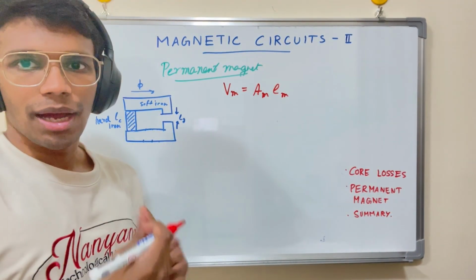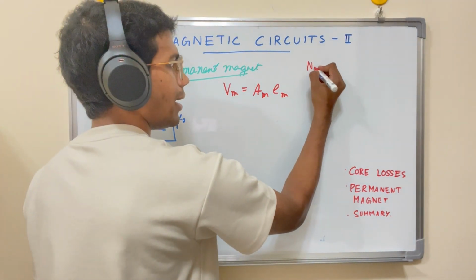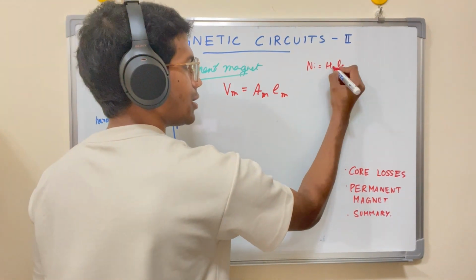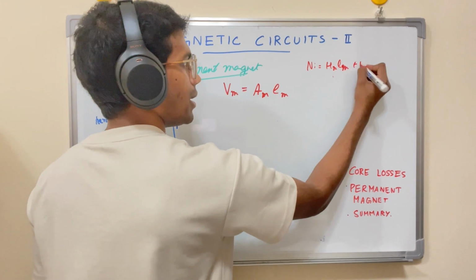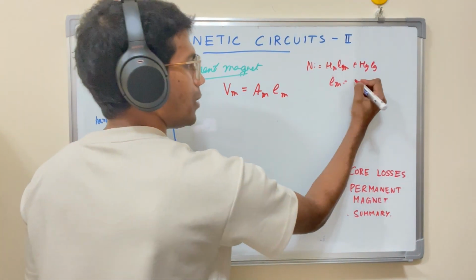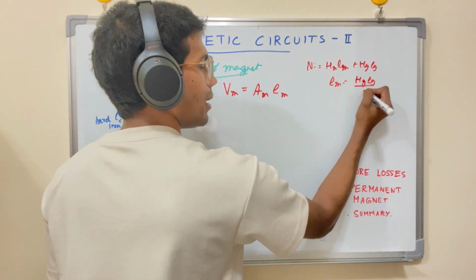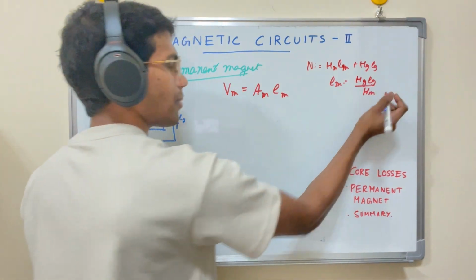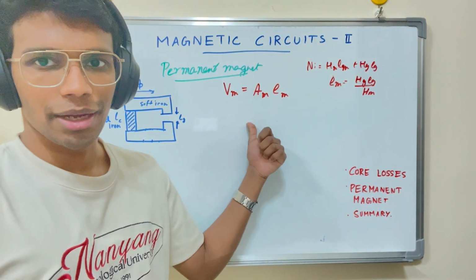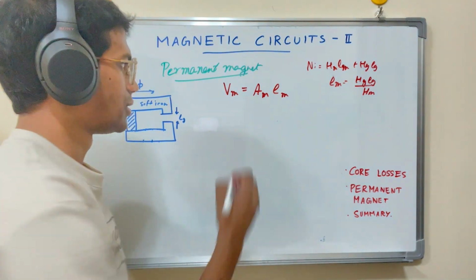That makes sense. Now we have Ampere's law, which states that Ni equals HClC, or in this case HM Lm plus HGLG. So we have Lm equals negative HGLG upon HM, and we're not going to use the negative because we're just going to substitute back into the volume formula, and volume can't be negative, so we're just going to go with the modulus there.